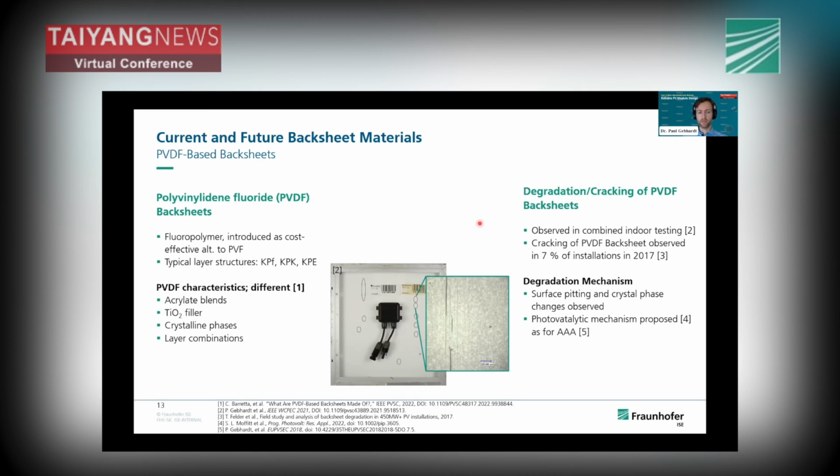There are already some publications about degradation and cracking of these backsheets indoor and outdoor from a large field survey, which is of course not 100% representative of the installations around the world, but it's the largest we know. And they found that 7% of the PVDF backsheets were cracking in 2017.